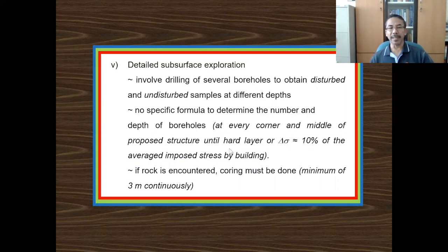In terms of depth, normally they drill up to a hard layer, or some people refer to the depth at which the stress increase due to the proposed structure is about 10% of the stress of the proposed structure. You may refer to the topic of stresses in soil that you have learned in soil mechanics class.